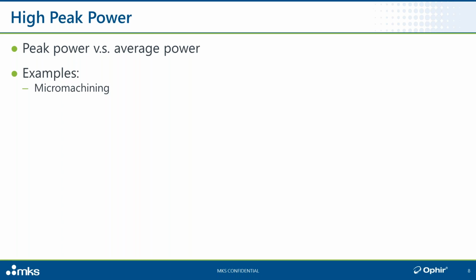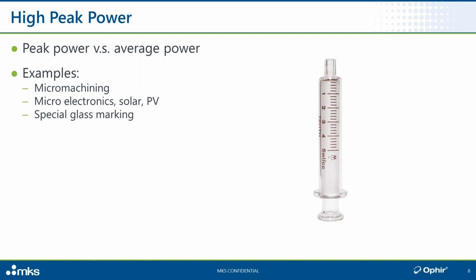So micro machining, there are increasingly interesting applications there. An interesting application I came across not that long ago is certain types of marking of syringes. What they do is use ultra short pulses which locally change the refractive index of the glass, to give the appearance of printed symbols. And this creates some seriously challenging requirements when it comes to measuring them, because the absorber materials that the sensor would be based on need to be optimized for this sort of thing.